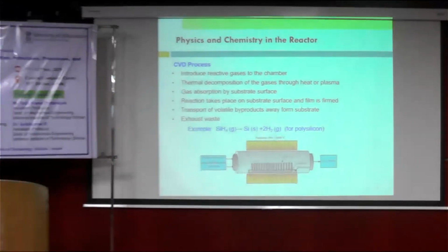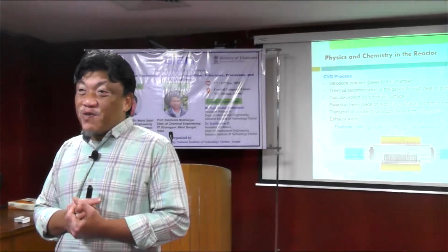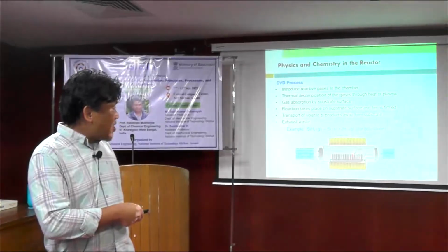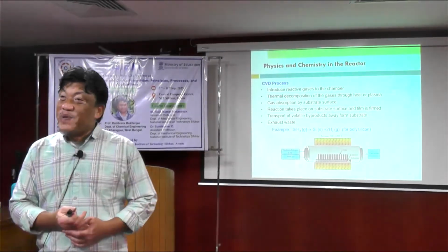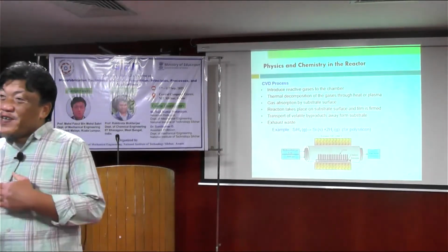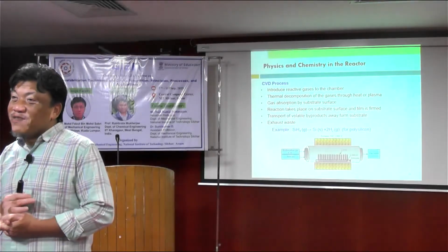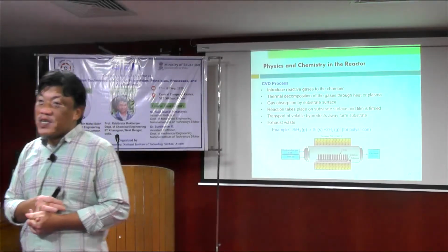I don't think it will create turbulent flow; it's just laminar, steady flow inside, because it's very slow, 1 liter per minute. But the issue is towards the end of the chamber, the concentration will normally be less. So you have some non-homogeneous deposition towards the end of the chamber.